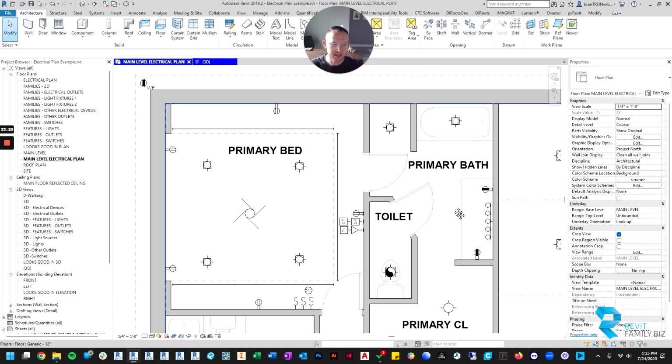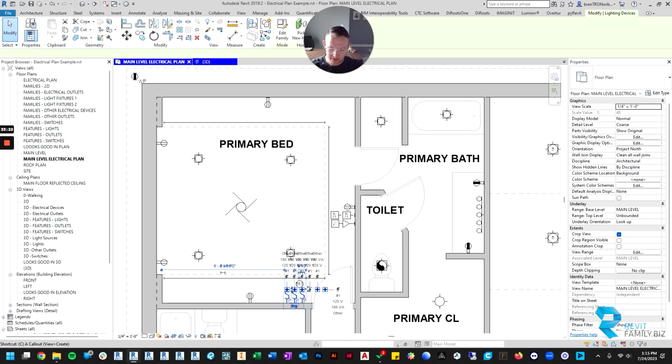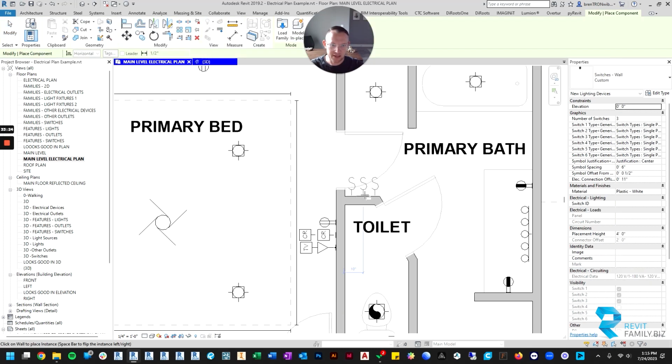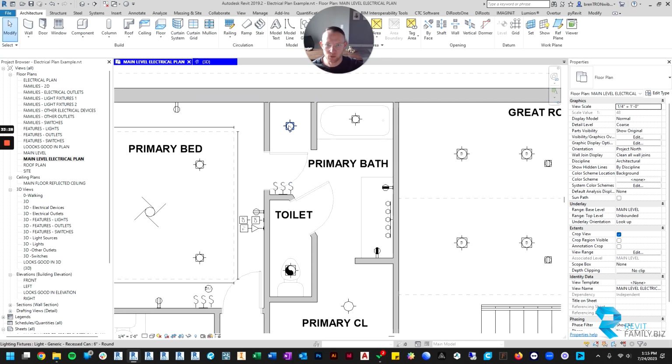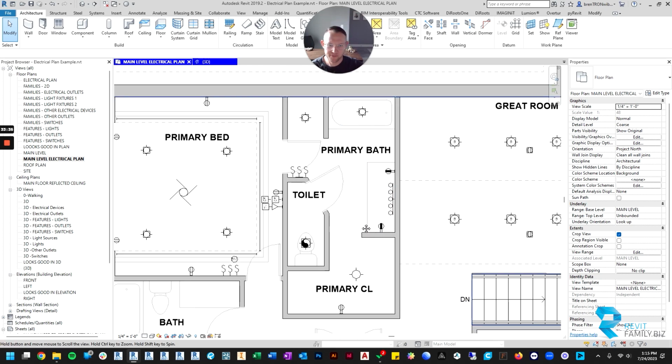All right, so then let's do the bathroom. And most likely we'll put the switches on this wall. And how many switches do I need? I need 1 for the shower, 1 for the bath, and 1 for the vanity. Let's say those are all in a different circuit. And so probably 3 single poles is fine.